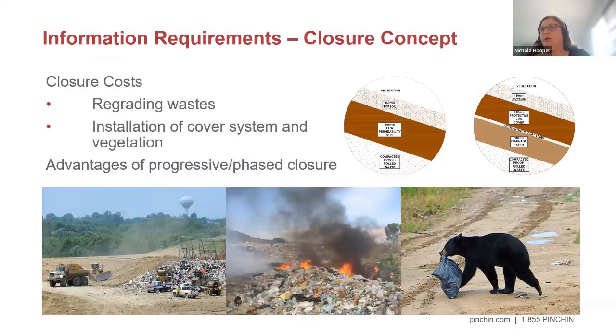Okay, the closure concept. There are closure costs associated with closing a landfill. Most jurisdictions require that some sort of cap or vegetation is placed on top of the landfill when it is closed. And this is why there are advantages to doing the progressive closure of the landfill or doing the phased closure of the landfill. So like working section by section by section.